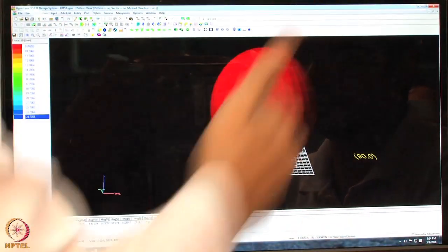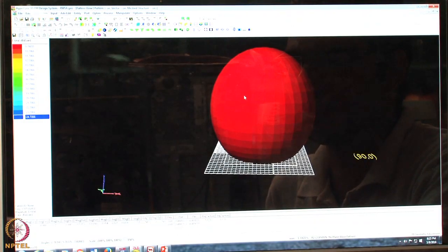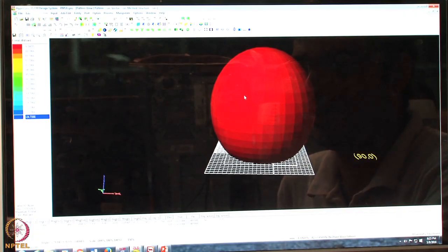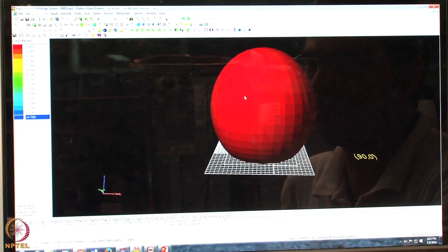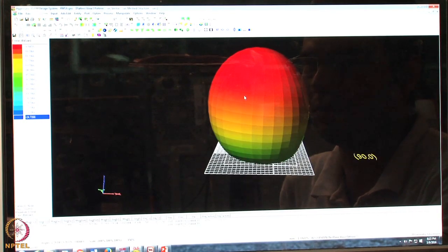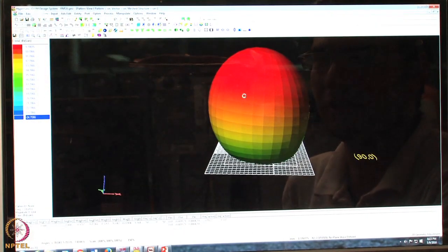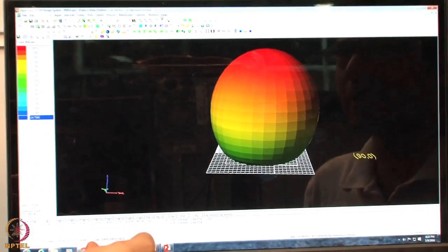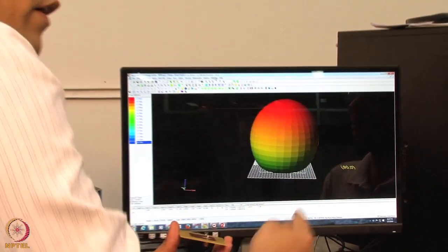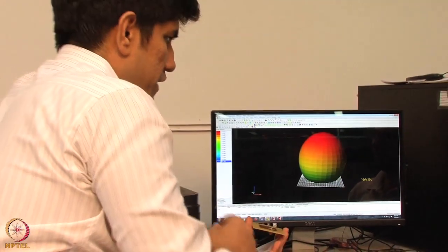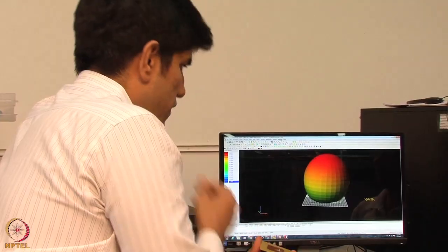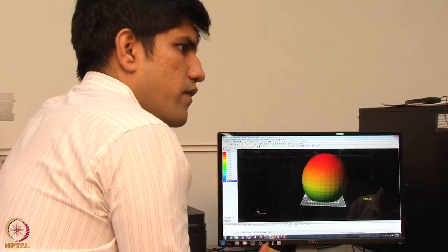If you go higher up in the frequency, at 2.015, you can see this, and this is 2.021 gigahertz, 2.05. Then the gain starts to decrease again. So initially the gain is low at a certain lower frequency. We can also see its gain plot. It's going to change, and then at some point the maximum gain appears at a certain frequency. Yes. So at which it is resonating.